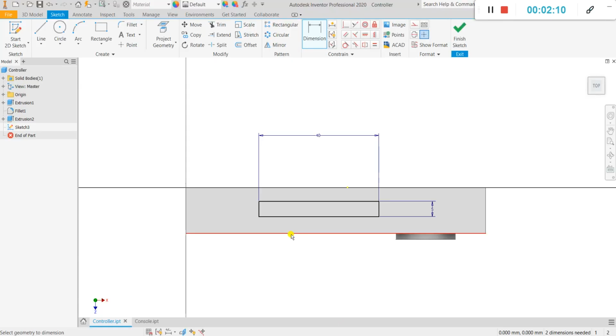So in Inventor, I could use the dimension tool, hover over the side line till it goes red, click, move inwards until that's red, click, and then just move down here into this white space, click again, and I could amend that to 30 and then click on this little green tick when I'm happy. So that's moved this rectangular profile inwards from this edge to here to 30mm.